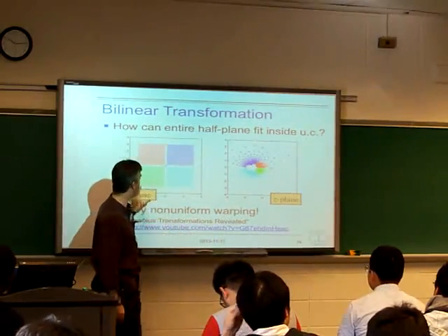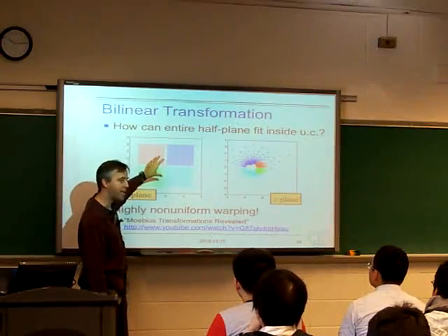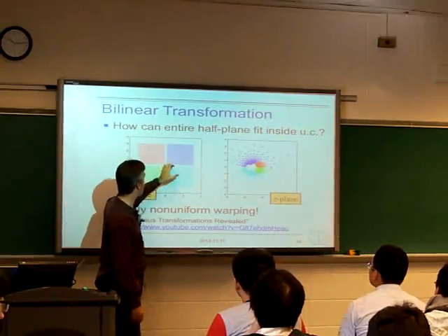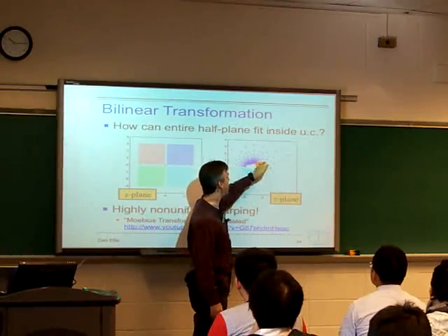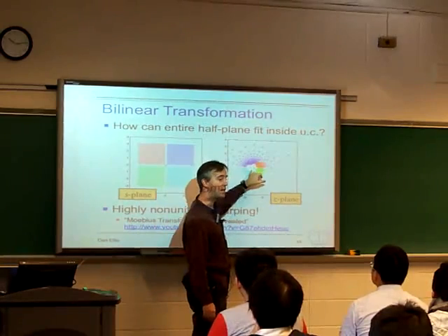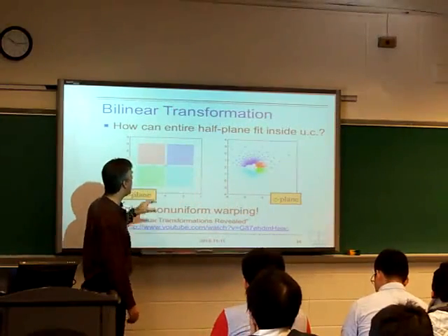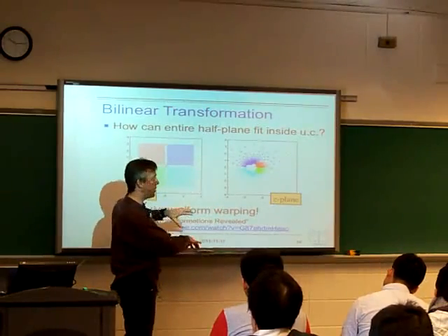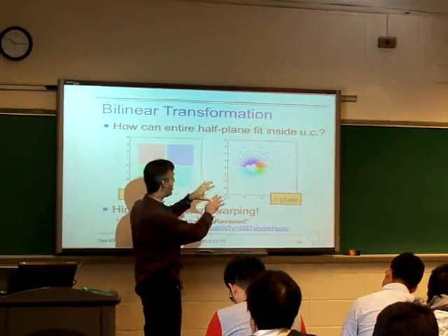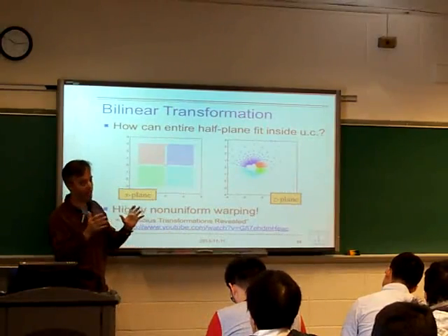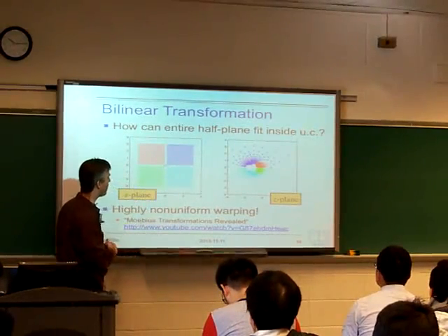So we construct this mapping between the S-plane and the Z-plane, such that if we have this polynomial on the S-plane, defined by a set of poles and perhaps zeros, that gives a particular set of values on the imaginary axis, we're going to get the poles and zeros now placed on the Z-plane, such that we get those same values on the frequency axis in the Z-plane, that is the unit circle. And so the bilinear transform is this mapping between these two planes. It's this one-to-one mapping, but this fairly weird, mind-bending mapping that manages to move the whole plane around, although maybe it's not that impossible to understand if you remember that little video about the sphere with the light projecting through the points on the surface of the sphere.